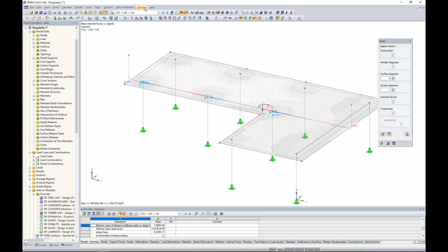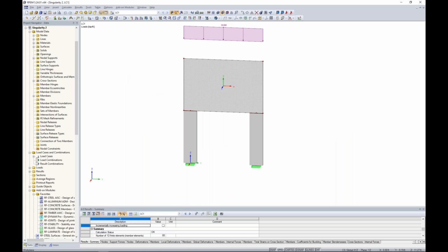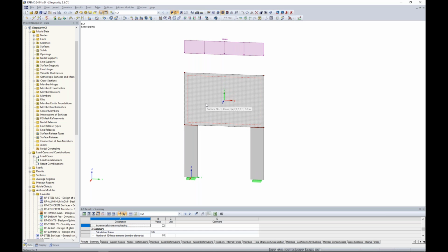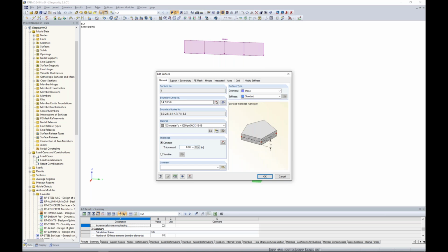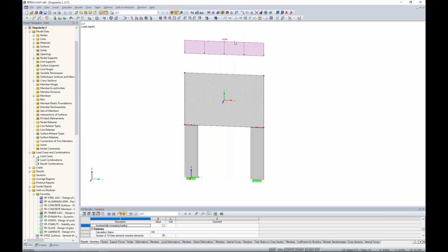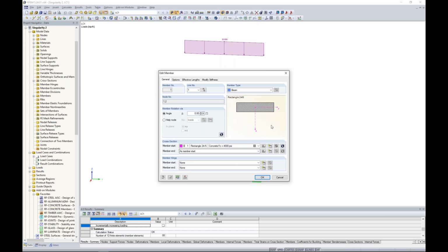So moving on to our next example, also to deal with singularities, there are situations where maybe average regions don't help in certain scenarios. For this particular case, we have some type of shear wall or gravity loading wall, and we have 4,000 psi concrete 6 inches thick, and you can see just a simple gravity load applied. The top here is a distributed load. And I've also applied a couple columns framing into the bottom.